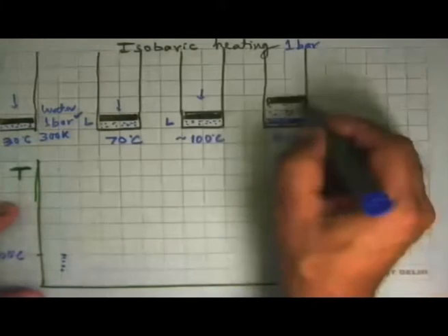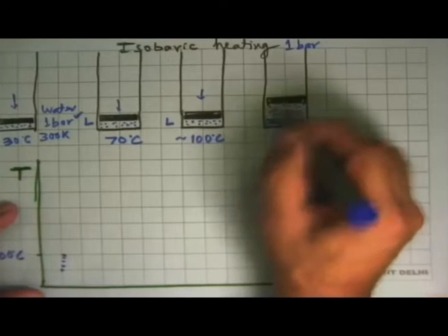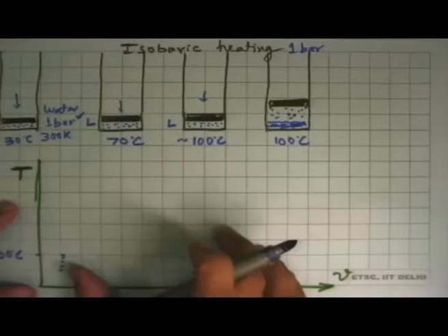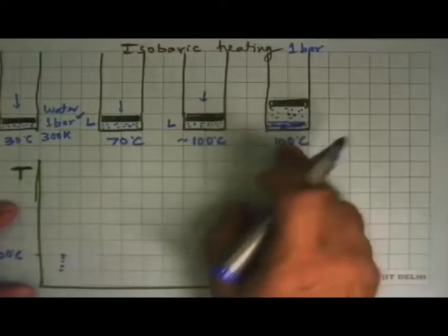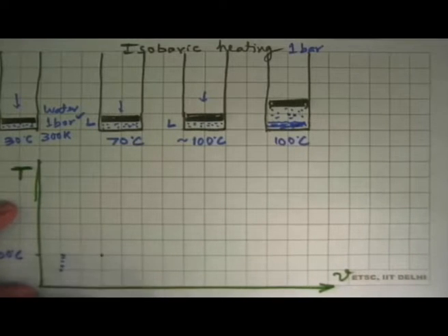So what we will do on this diagram is say, well, I'll just plot the total volume of this. So my mass is the same, volume has increased, so specific volume, meter cube per kg, will increase and increase a lot without any change in temperature. So this state will now start moving along the 100 degrees Celsius line and say come over here.